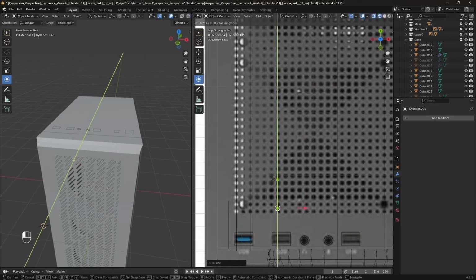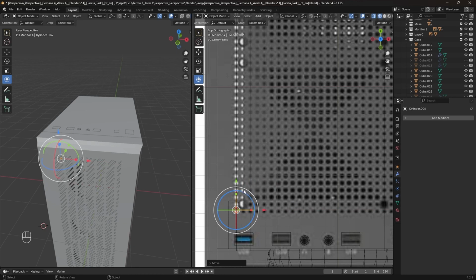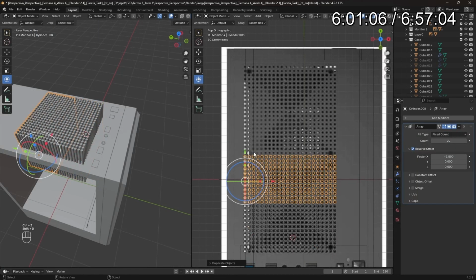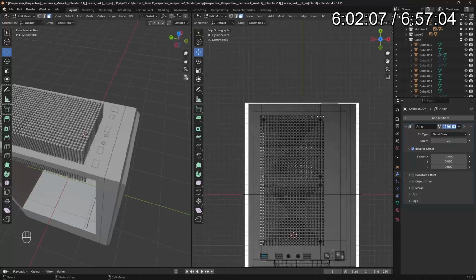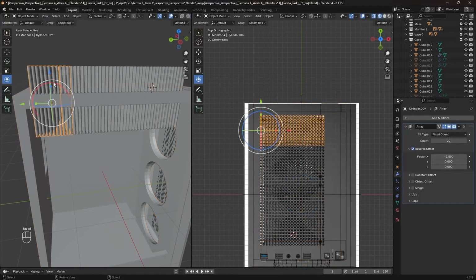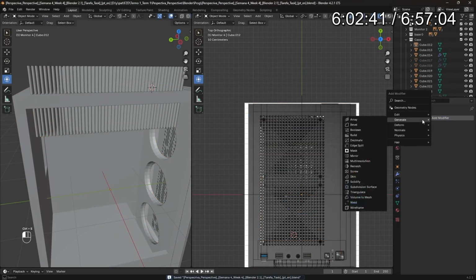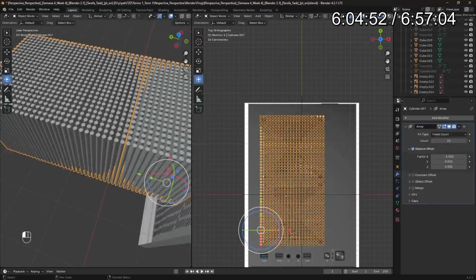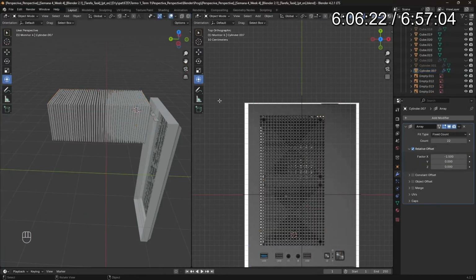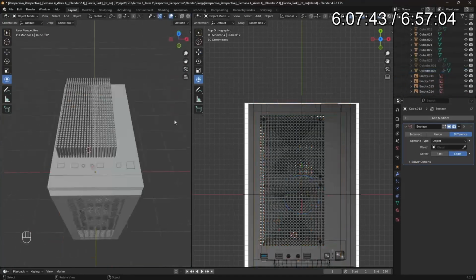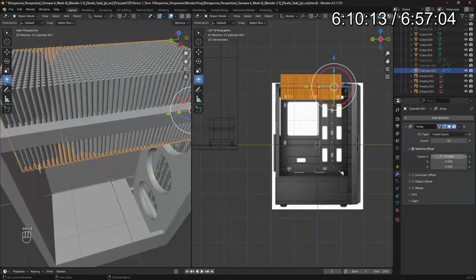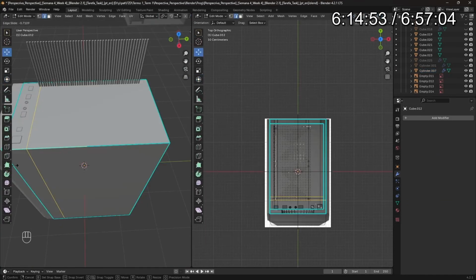My idea over here was just to do this pattern on the top part using a cylinder and also the boolean. So what I did was just using array, and then I started duplicating it. I faced the same problem that I faced on the previous part. To fix it, I selected a specific part of the mesh, and I literally applied the boolean just to that part rather than trying to apply the boolean to all the mesh. So let me show the specific point.